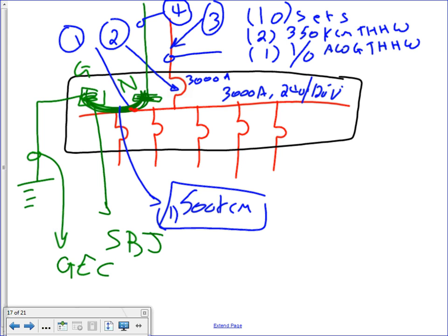But for the time being, remember, at the service panel you must bond the neutral to the ground. You have a conductor coming from the ground bar. There will be a grounding bar inside your panel. You take a wire from it to the ground rod, a rod into the ground, and then you tie the ground bar and the neutral bar, two bars like this inside your panel, one neutral, one ground, with a wire. Tie the two together. That's called the main bonding jumper.